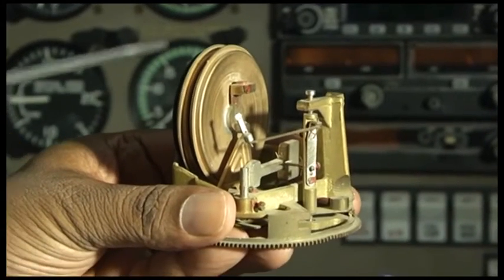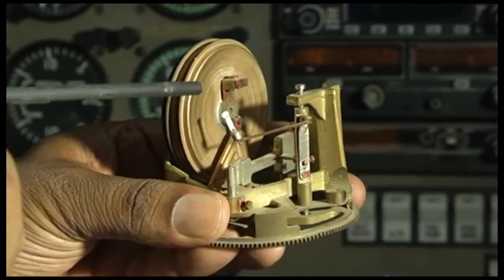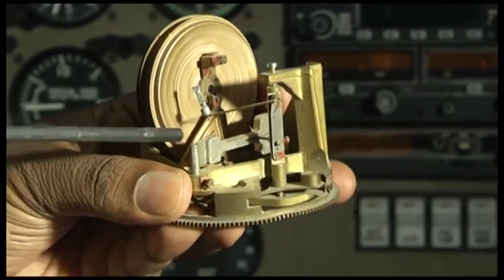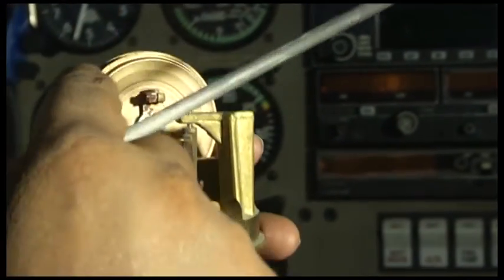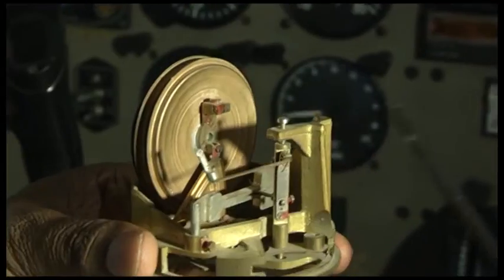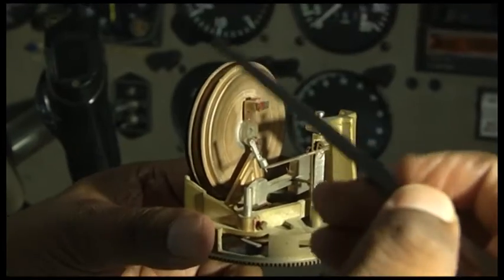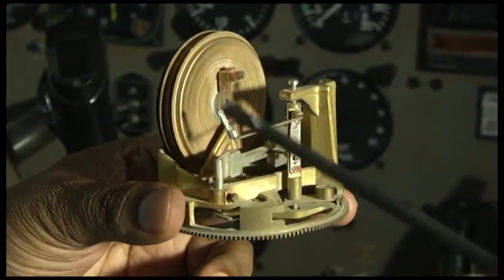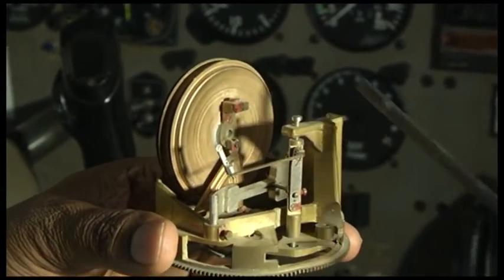The movement of this diaphragm is transmitted to the pointer by mechanical linkages consisting of link, rocking shaft, vertical bimetallic arm, sector and pinion. There is a hairspring also fitted to remove the backlash error. As the differential pressure increases, the diaphragm expands and rotates the rocking shaft, which through the sector and pinion moves the pointer across the instrument dial.